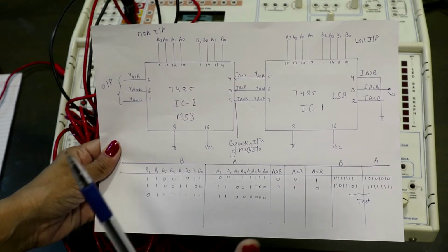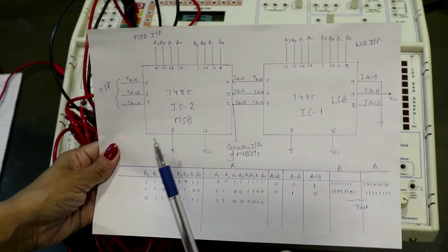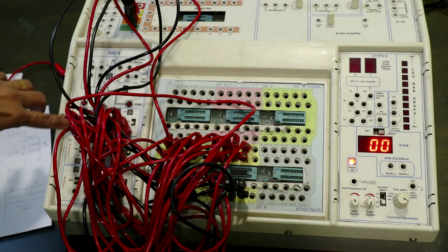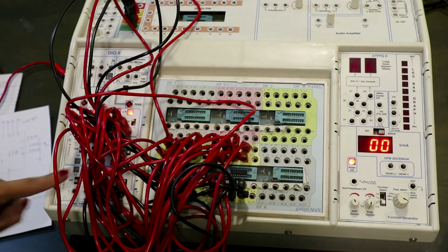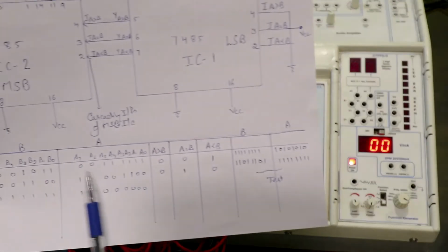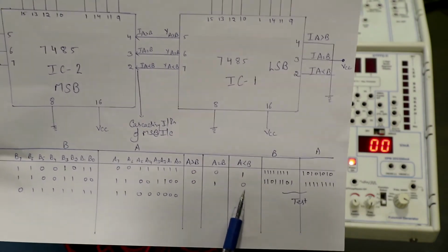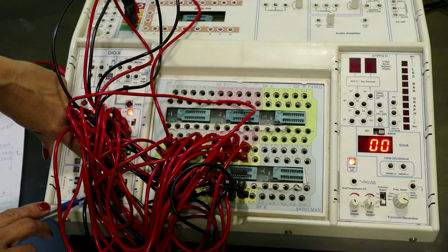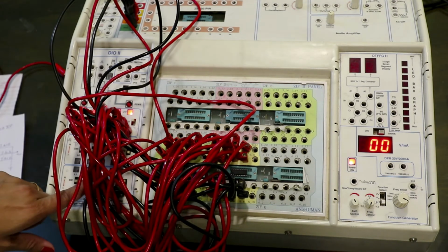For a basic truth table, we are going to make first B all 1, right? We know this first row of our input, we used it for B. So I make it on, right? And I keep A values as 0. So that easily we can verify that yes, A is less than B. So see here, this last connection is for A is less than B. So this LED is on. So we have tested this.